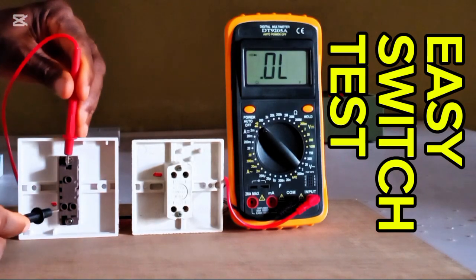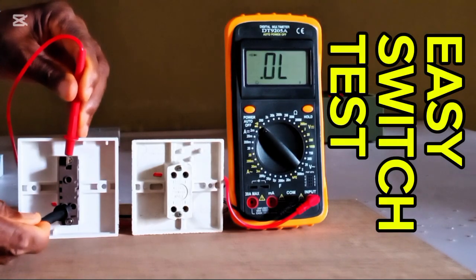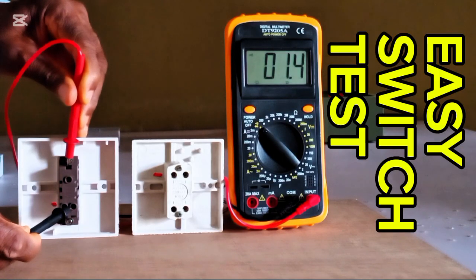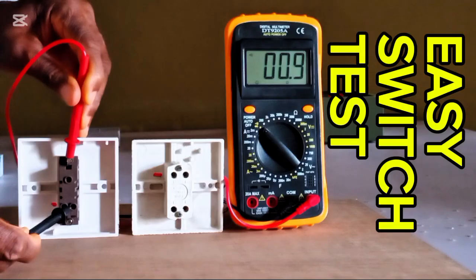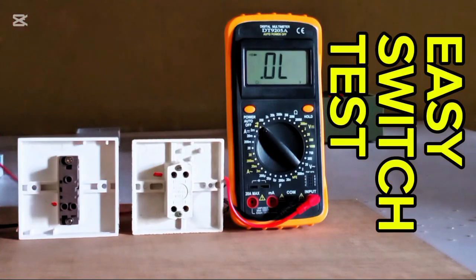Okay, now the common to line 1 that initially read is now out. It's not reading. So let's test common to line 2. All right, so common to line 2 is now reading. Each time common to line 1 reads, common to line 2 should be open. Good. Now common to line 2 is reading, common to line 1 is open, as we can see. No reading at all. All right, so this is when the switch is good.